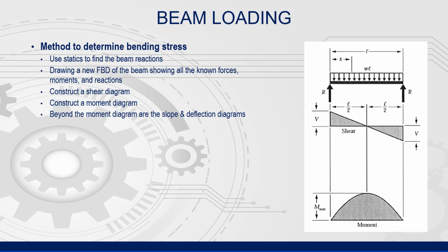The method of creating the free body diagram, followed by the shear diagram, and then the moment diagram, allows us to use a graphical method to determine maximum moment without any other tools or computations. The other options are to either double integrate the functions, look up values from tables, or use analytical software. The beauty of the graphical method is that it works for nearly any load configuration.